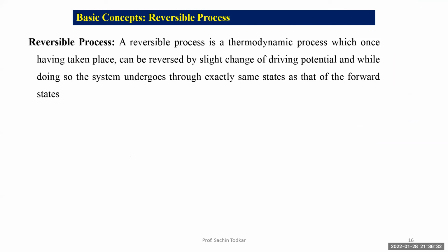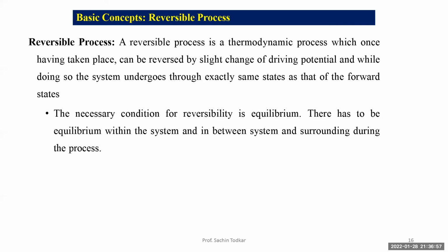Reversible process. A reversible process is a thermodynamic process which, once having taken place, can be reversed by slight change of driving potential, and while doing so, the system undergoes exactly the same states as those of the forward process. So in a reversible process, the process path will be followed as it is. The necessary condition for reversibility is equilibrium. There has to be equilibrium within the system and in between system and surrounding during the process.